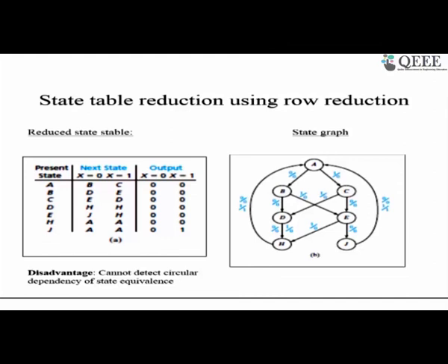Why do we use serial input and serial output circuits? See, that is for several reasons. Once, the complexity of the circuit can be reduced because the number of inputs it takes and the number of outputs it gives out is reduced. Or the requirement may be that as soon as the LSB of the BCD has come, we want the LSB of the XS3 to be available.